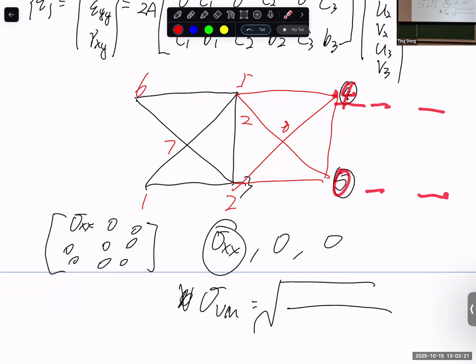And then in the node set definition, you put these nodes as, let's say, node set 1, and you put 4 and 5 in it. And then in the force applied, you will have node set 1 and force applied in x direction, which you put 1 there. And then what is the magnitude of force applied? Let's say 1000, you put 1000. Yes, this is how we apply the force at these two nodes.